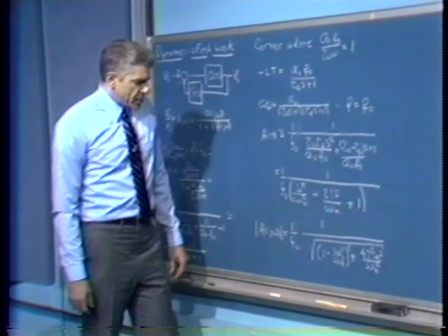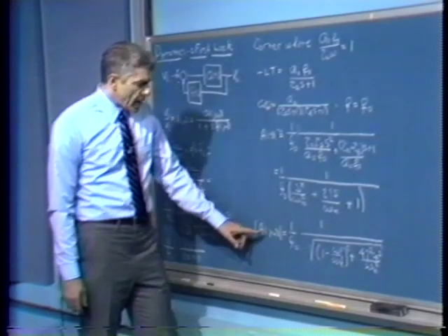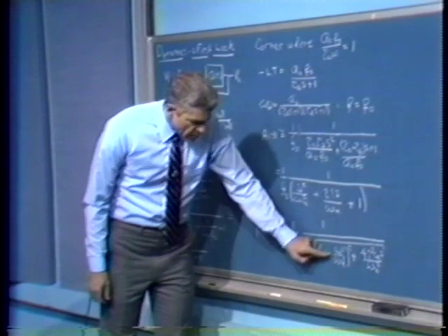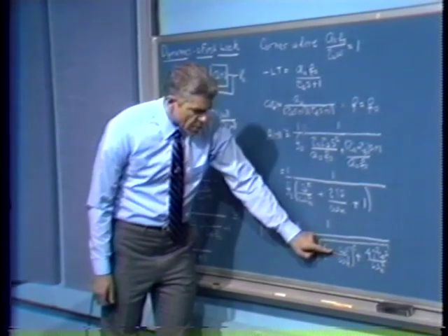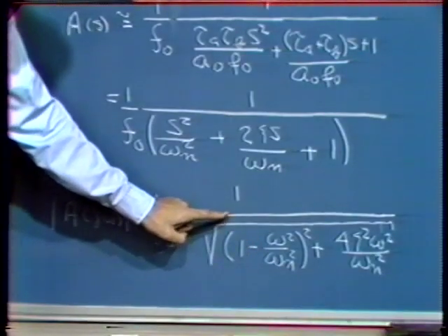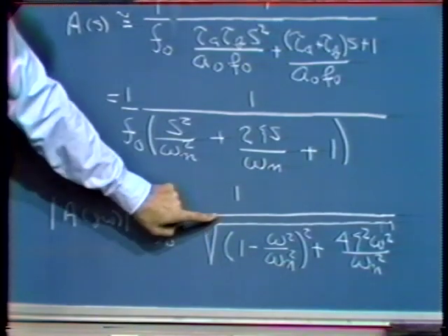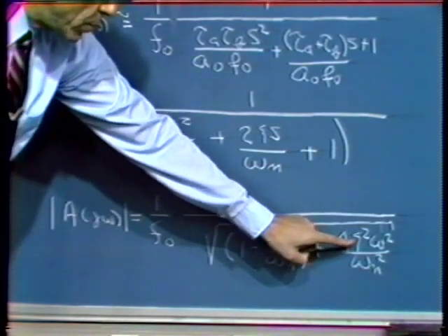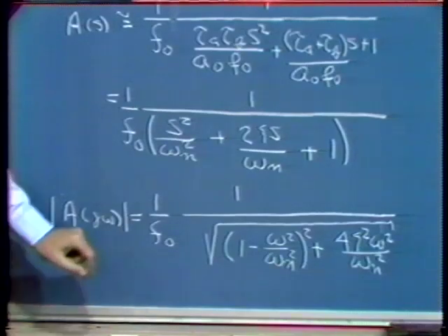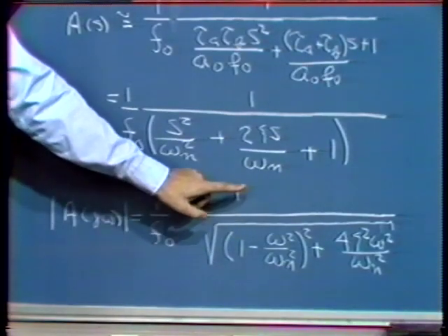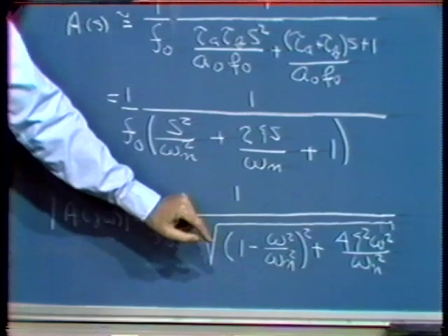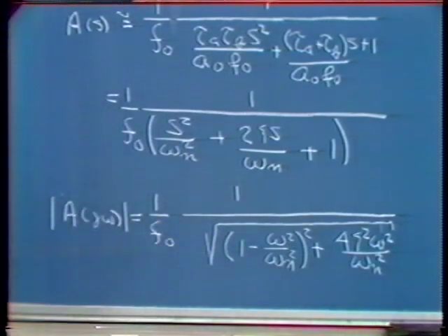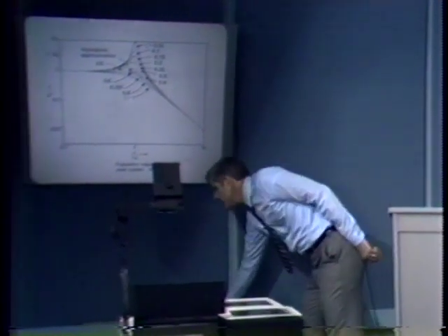At the natural frequency, in other words, if we excited our system at its natural frequency, the real term in the denominator would go to 0. And in fact, there's the possibility of a very large amplitude out of the term for systems with small damping ratio. When the real term is 0, we get simply 1 over twice the damping ratio for the magnitude of a second-order system. So we have the possibility for resonance, of course, with a second-order system. And we see that behavior in our Bode plot.